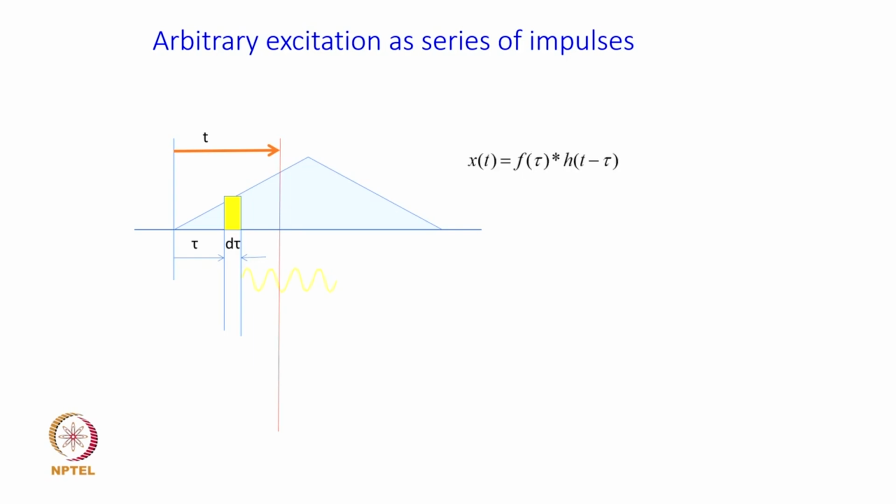Now, if I take the next subsequent impulse, piecewise linear, meaning that even if there are small changes here, I assume it to be constant of certain amplitude, I will check the response due to this impulse, which follows the impulse shown in yellow.